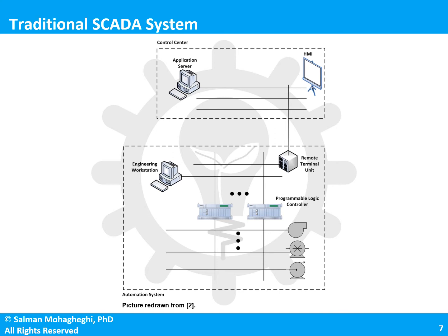So these are known as 4 to 20 milliamp live 0. Traditionally, in SCADA systems, all the connections were hardwired. So if you had devices that would have to connect to multiple other devices, between each pair there would have to be a physical wire, physical conductor that would connect the two. As you can imagine, this would make the design complicated. More importantly, the troubleshooting would be very complicated. So if, for example, you would notice an inaccurate signal somewhere, it would be very, very difficult to go back and figure out what wire might be having issues.